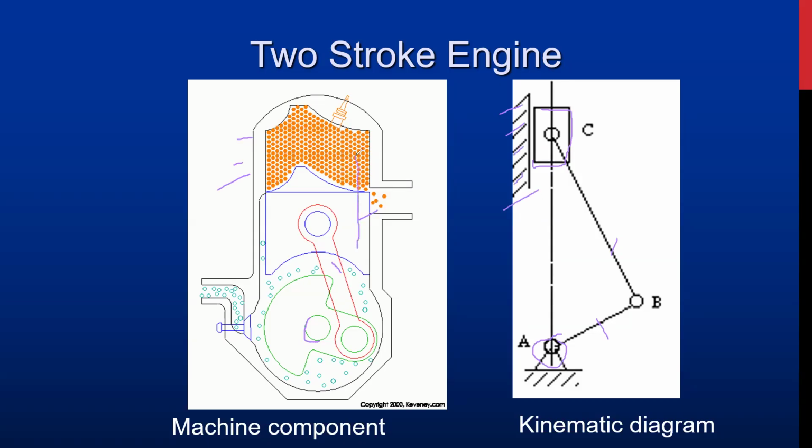So now this one is sliding through, which is this part C, and then these are the other parts, and these are the other joints, right? All right, so this is the joint that is connecting. There's joint one, there's this joint, and there is that joint, right? So now this is a simple way of representing this complicated two-stroke engine as a simple kinematic diagram. Please make sure that you acquaint yourself with drawing these diagrams.